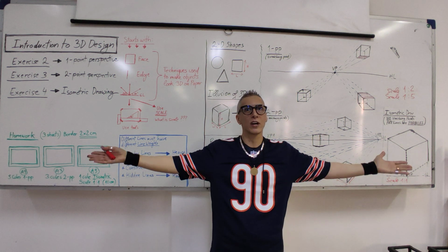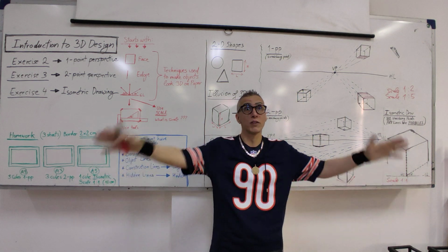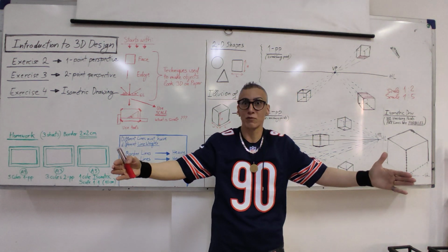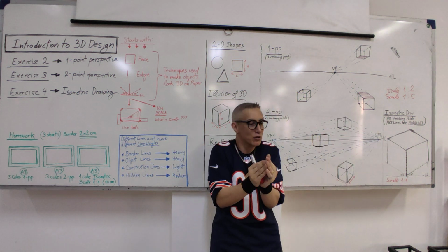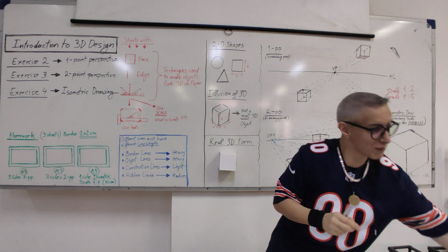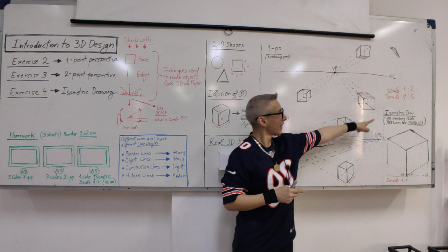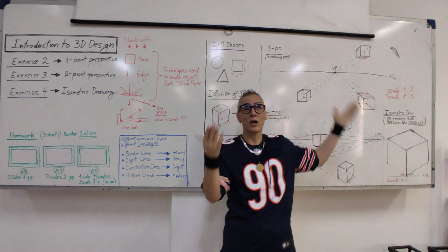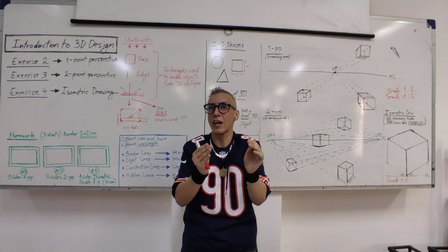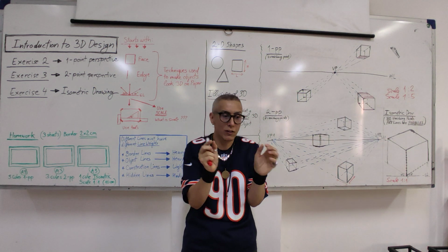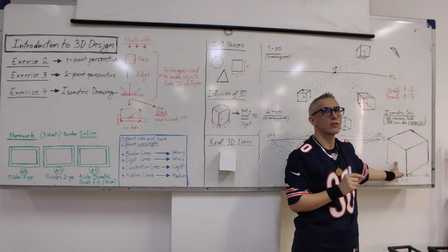Now if you want to draw Yarmouk University, all of it, as a plan view, for example, or as an isometric, then you need to scale all of Yarmouk University down into this paper. You need to use a scale. Maybe 1 to 1000 or 10,000, I don't know, okay? So the bigger it becomes, the scale must also be increased so that it fits into the paper. But it is still 100% correct.